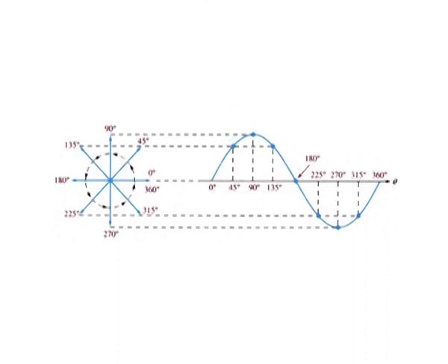This figure here shows how the phasor traces out the sine wave as it goes from 0 degrees to 360 degrees. You can relate this concept to the rotation in an AC generator. Notice that the length of the phasor is equal to the peak value of the sine wave. The angle of the phasor measured from 0 degrees is the corresponding angular point on the sine wave.